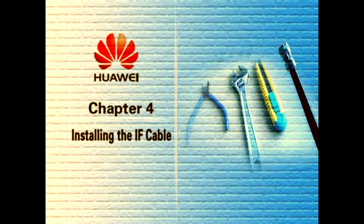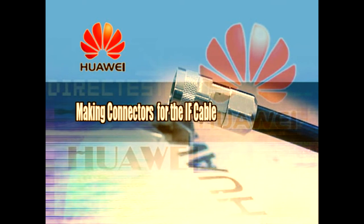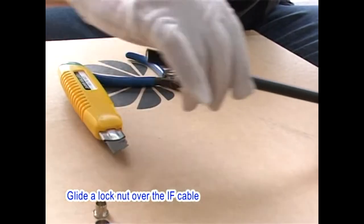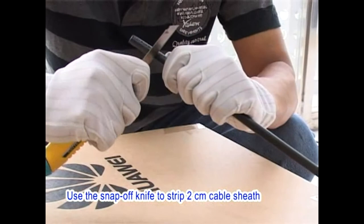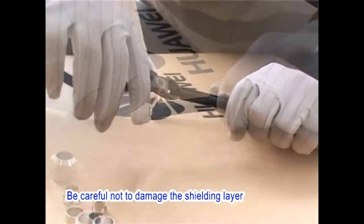Chapter 4. Installing the IF cable. 1. Making connectors for the IF cable. Required tools are wrench, snap-off knife, diagonal pliers, and file. Glide a lock nut over the IF cable. Use the snap-off knife to strip 2 cm of cable sheath. Be careful not to damage the shielding layer.